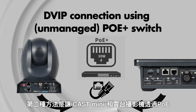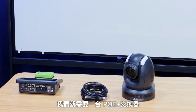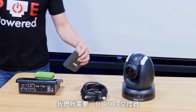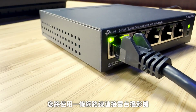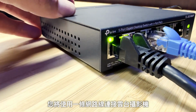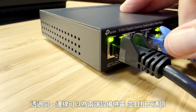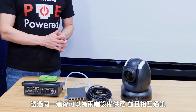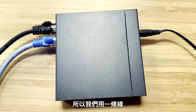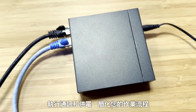Now, the second way to have the iCAST Mini and a PTZ camera communicate is through PoE. And to do this, we're going to need a PoE plus switch and an additional Ethernet cable. So you'll have an Ethernet cable connected to the PTZ camera, and then you'll have an Ethernet cable connected to the iCAST Mini, and it will power each device through the same connection that lets both devices speak to each other. So we have one cable doing the communication and the power to simplify your workflow.